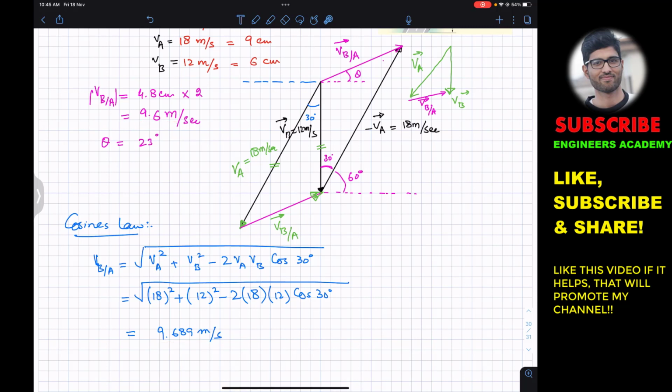Since the ruler can measure the length up to 1 decimal place, that is up to 1 millimeter, we will get the answer 9.6 meters per second using the ruler. But using the calculator we can find the answer more accurately. So the velocity of B relative to A magnitude is 9.689 meters per second.